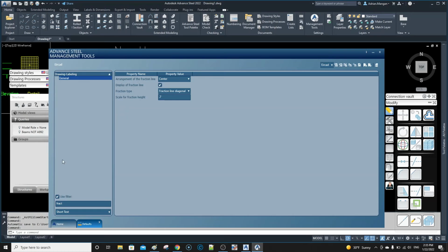And then the development view is an important one. So I guess development, I think it's view radius. No, that's not it. View radius. Let's try radius. So it's going to be the dimension, and it should be development view radius. There it is. So you want to set this to the inner dimension. Most bends are bent from the inner dimension, so the inner dimension makes sense unless you have to change this. That's the general consensus with that. It's not just my opinion.